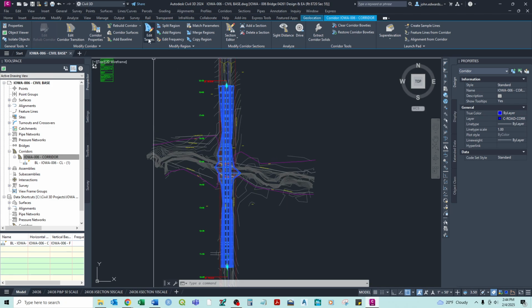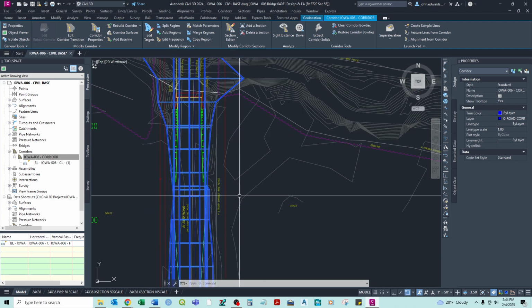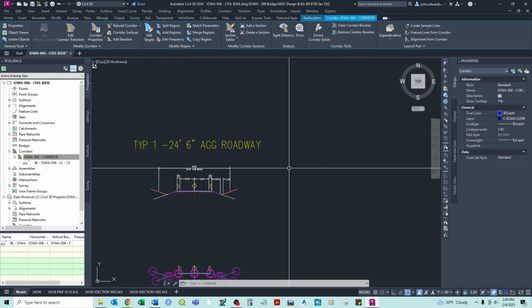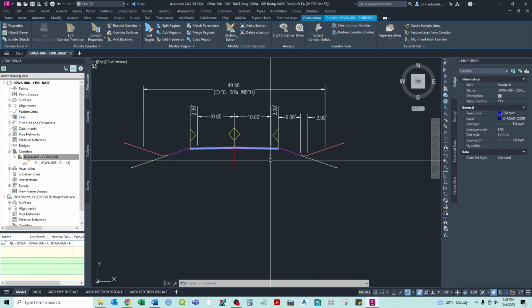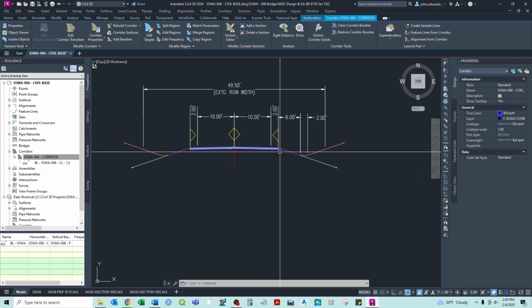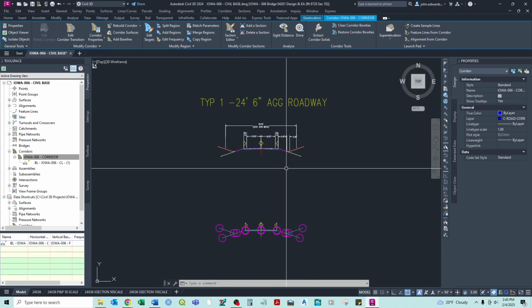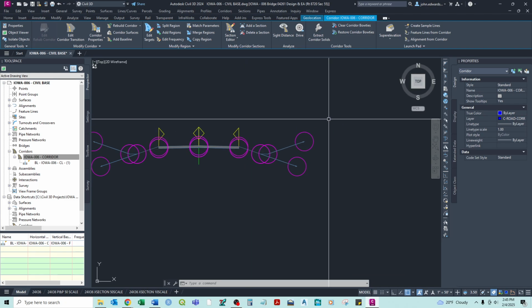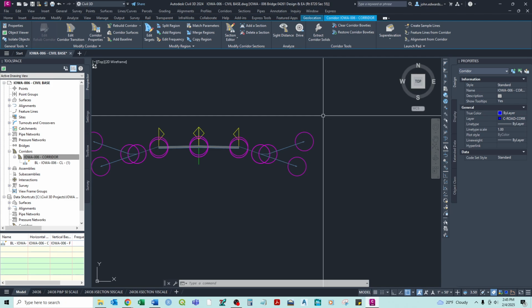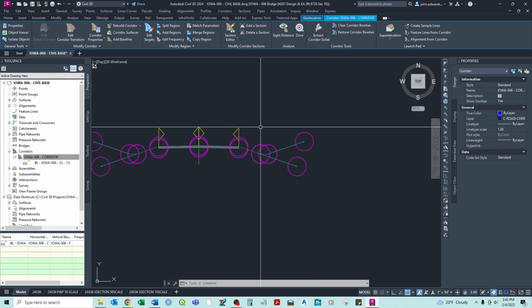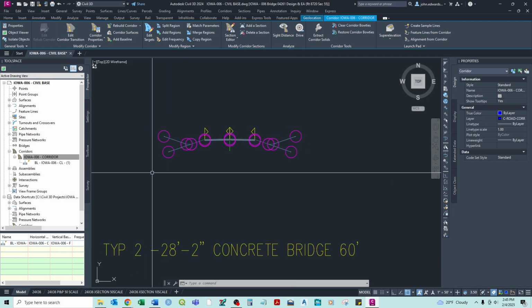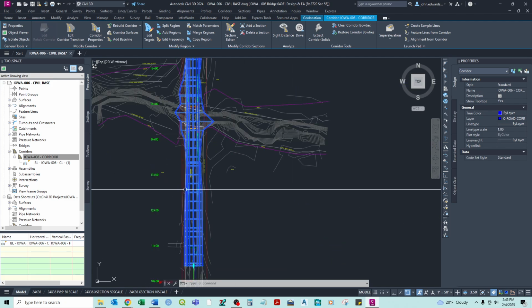We'll talk about targets in a minute, but briefly, your targets are, and I believe we discussed this briefly in the last video, when we set features outside of our lanes, and even the edges of our lanes, remember there were all these markers. Well, they can be tied to specific features within our drawing, within our design, both surfaces as well as polyline or feature line features, that can adjust how these subassemblies operate. Okay, so that's what targets are.